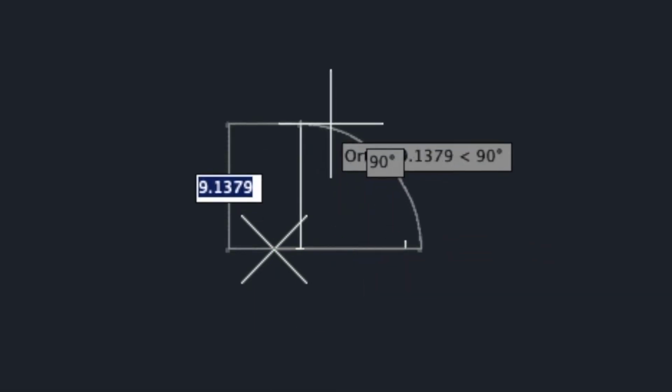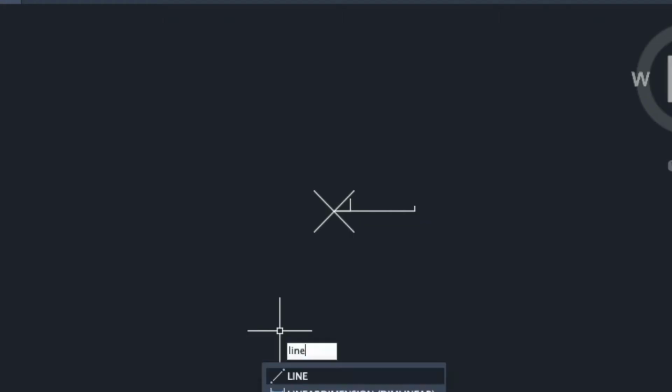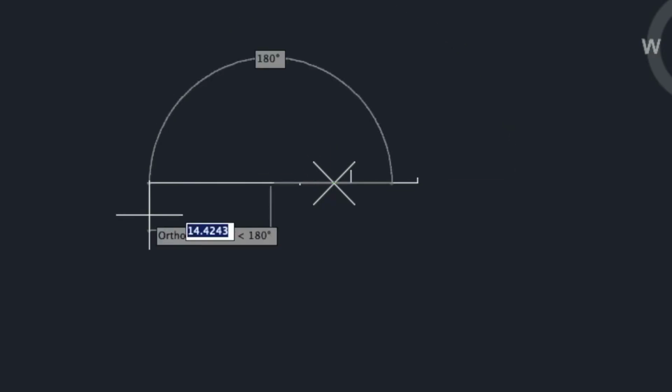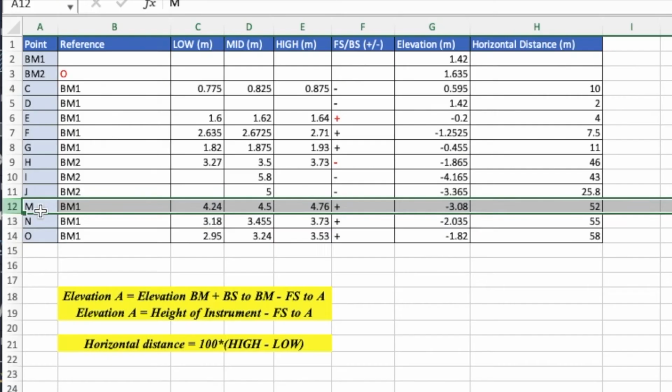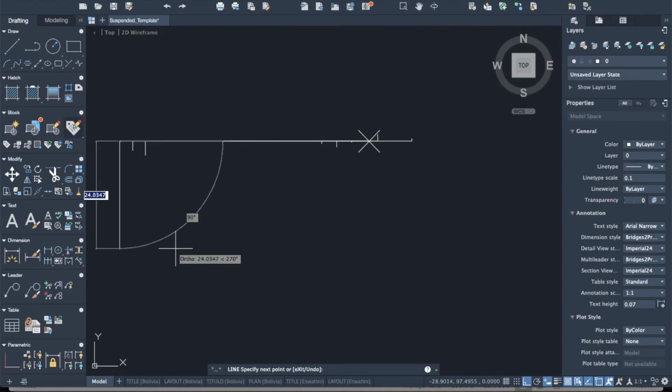The point at the bottom or at the top of the vertical line you drew is where your survey point is. Repeat this process for all survey points, paying close attention to which direction to draw the lines and to which benchmark each point pertains. Finish plotting all your points from benchmark 1. In this case, we will finish plotting all the points from benchmark 1 before moving on to benchmark 2.